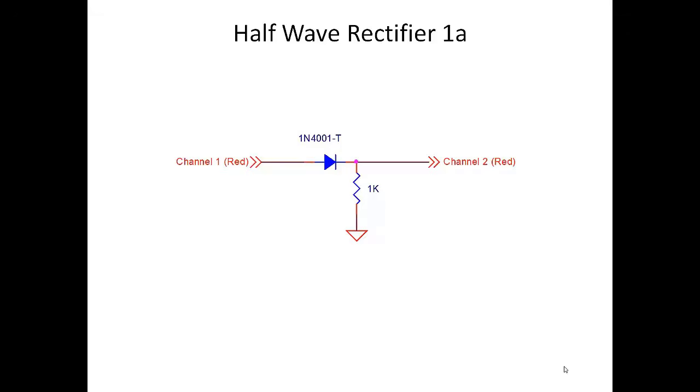Be sure to only measure the positive half of the voltage swing on the input signal for your comparison. We are not interested in the peak-to-peak voltage, but only the peak voltage, which is between 0 and plus 2.5 volts.